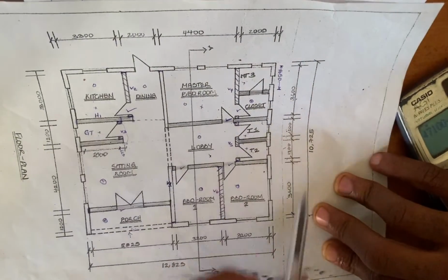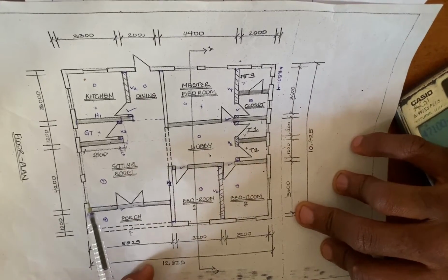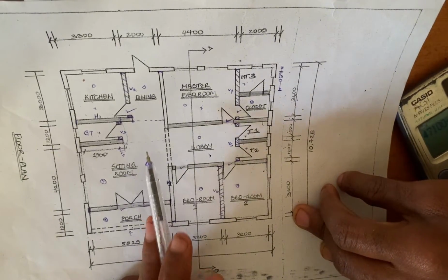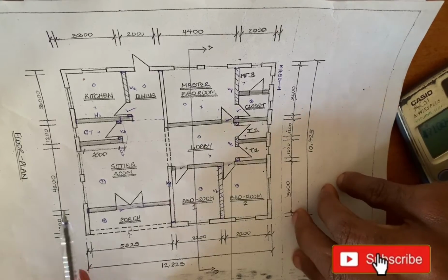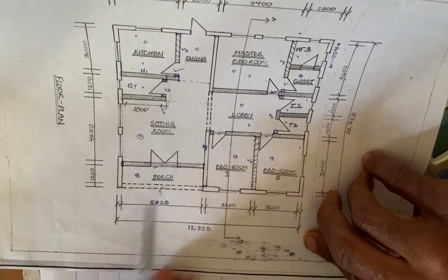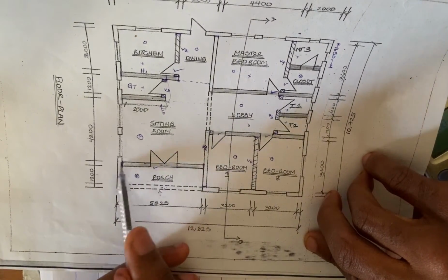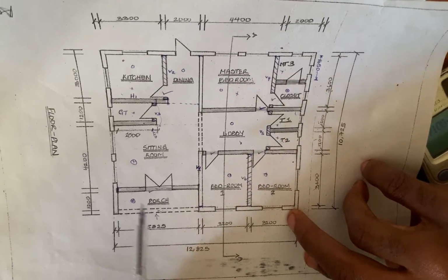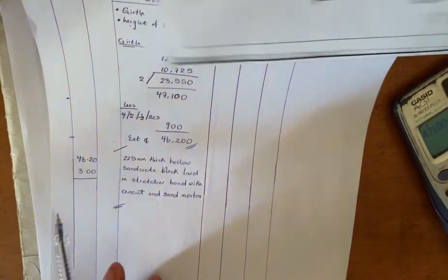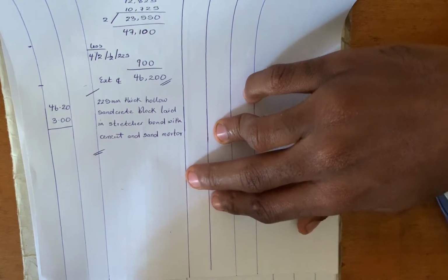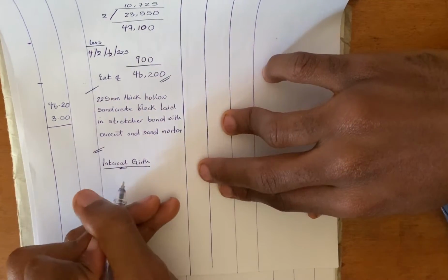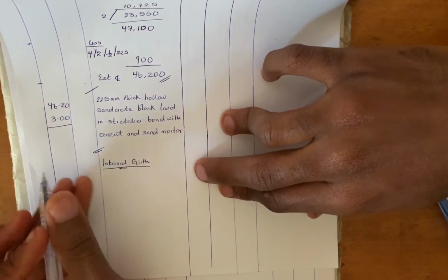is the internal block work, and like I said in the substructural works, we can calculate this by dividing the internal block work into vertical and horizontal blocks. So you know that we've already removed this block work and we've brought it to the external girth, so we are not going to be booking this in the internal. So now how do I calculate this? Let me start by using the vertical first. So to calculate my block work internally, I will start by taking the vertical walls first.